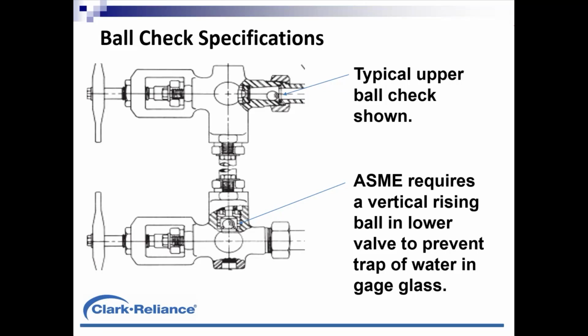So in the unlikely event of a serious leakage or failure, the water will push the ball up to its seat in the lower valve, and of course steam would push that upper valve up the ramp to its seating area. But when I say it's not a 100% shutoff, it really cuts it down to a whisper, or what we'll say, not a dangerous amount of flow when these ball checks do their job meeting these ASME requirements.